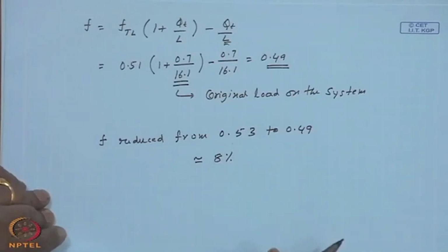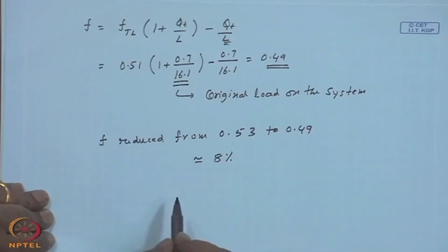Okay. So, as we have said right from the beginning, once again to repeat and to make you understand the logic behind it, we estimate the tank loss assuming a tank temperature. We treat the tank loss as a part of the load, recalculate the variables x dash and y, and use them in the phi bar F chart method to find the load fraction. That load fraction is the so called load fraction inclusive of the tank losses.